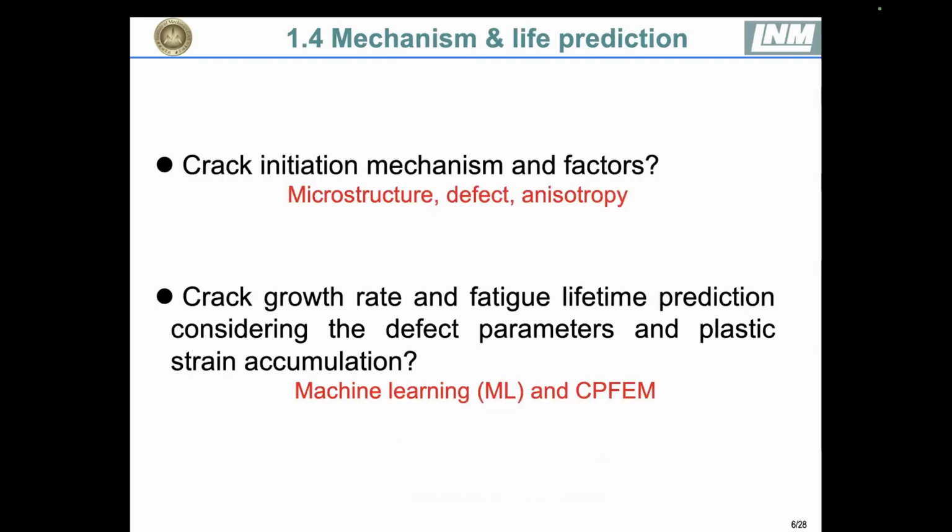In this analysis, we focus on two parts. One part is to analyze the crack initiation mechanism and some factors. We also study lifetime prediction for this material, especially the short crack growth part, because this is very important for very high cycle fatigue. It can take up maybe 80% or even 90% of the total fatigue lifetime.